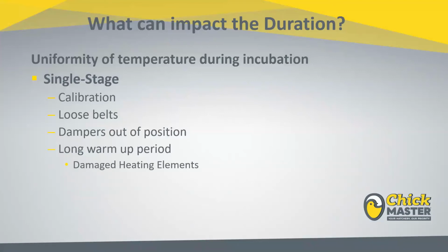I recognize this periodically when we look at graphing at individual hatcheries. And the thing to always remember is at least a couple of times a year during a routine maintenance check, make sure you force those heating elements to activate and take an amp probe and take a physical amperage reading of those heating elements to determine that they're actually functioning correctly.